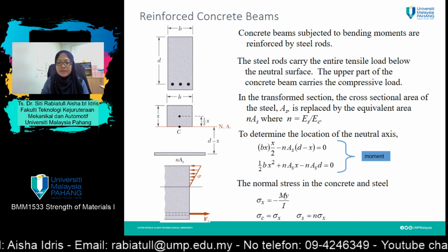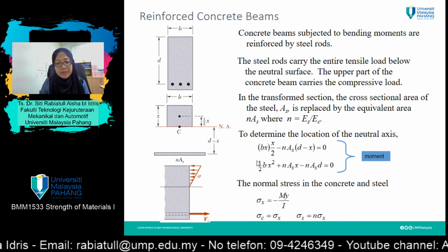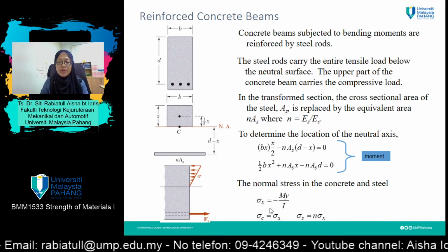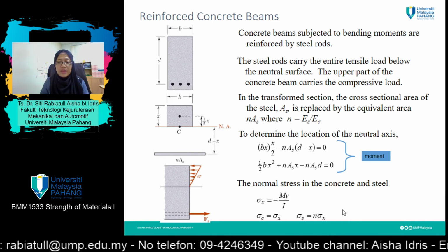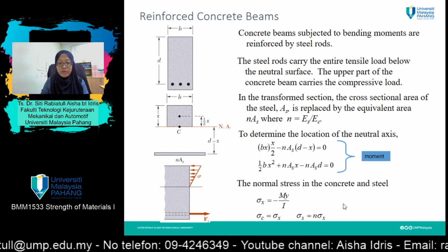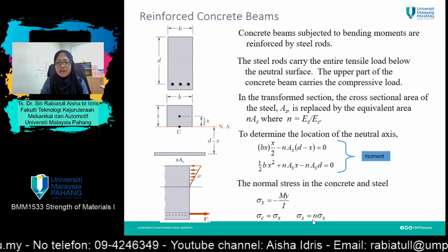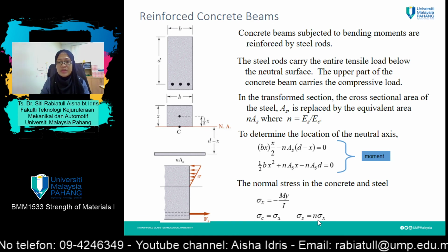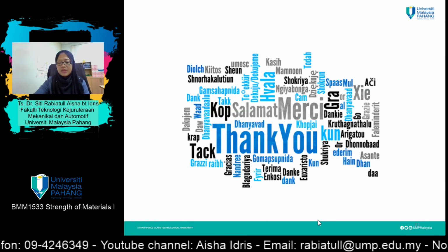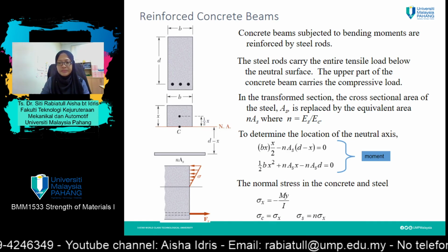After that, using the same flexure formula, sigma equals My over I. If we want to find the value of stress in steel, sigma steel equals n times sigma in concrete.